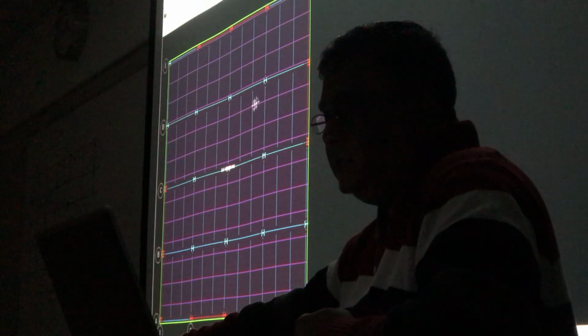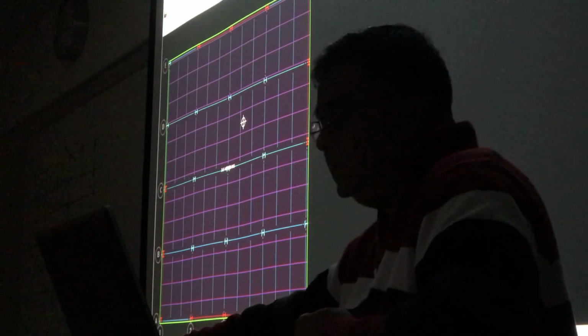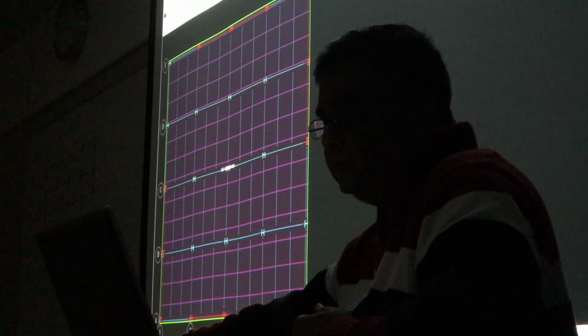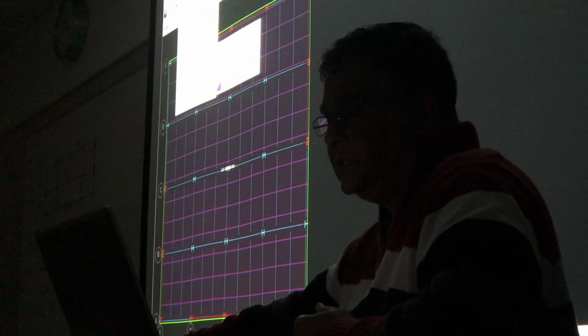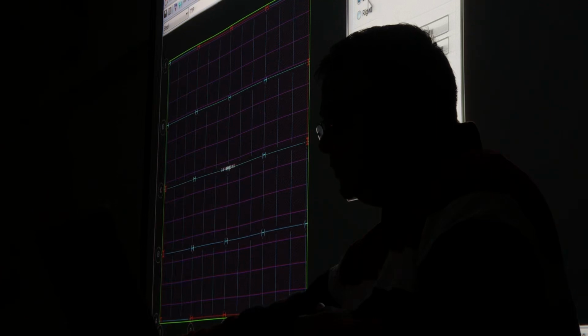Okay? So what I need to do, I need to open the slab. I did not show it in concrete, but listen. So go to slab opening, and I'm going to say that overhang 12 on the left, and if I'm saying that I have an opening, the opening should be inside the overhang, not outside.